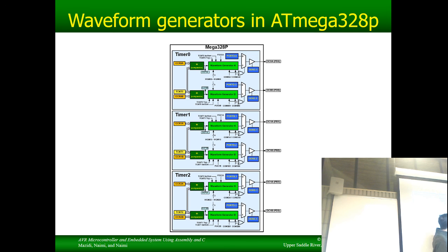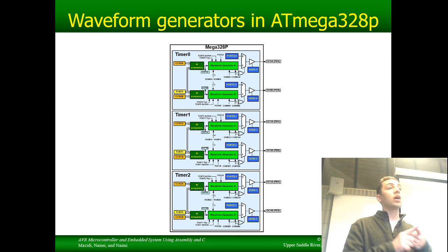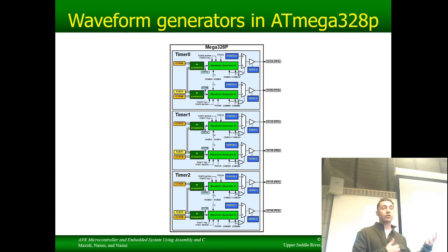D3, D5, and D4. You don't have to use timer 1 for this. Okay? So there's a little bit of math involved at the beginning. You're going to have to figure out what prescaler you want for which frequency. When you press a button, you're going to have it set up so that either you're polling constantly or there's an interrupt. Your call. One way may be easier than the other, depending on how you implement it.